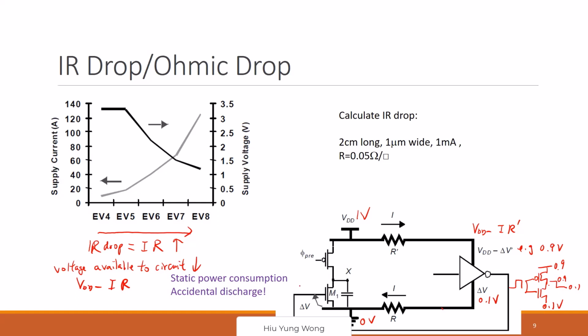Now this 0.1 comes to here. And this is a domino logic. This is a dynamic logic. I expect to have 0, then there will be no leakage during evaluation. But because this is 0.1, it will increase the leakage, right?